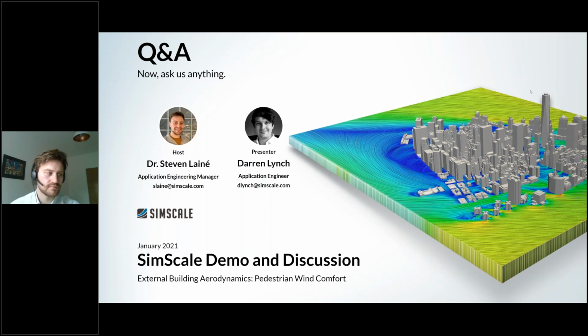Yeah, definitely. It should also be noted, of course, that we've got the Lattice-Boltzmann method, which is what the pedestrian wind comfort is based upon. And of course, this gives you full control over that. So if you wanted to upload an atmospheric boundary layer of any reference speed, then that's absolutely possible as well.